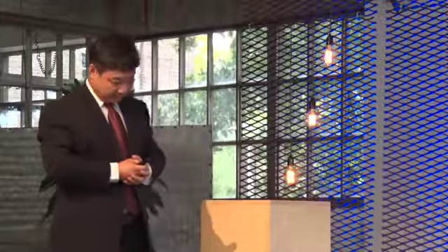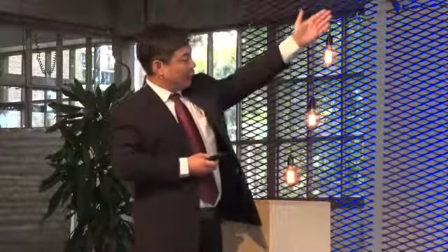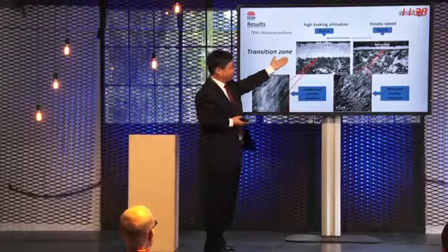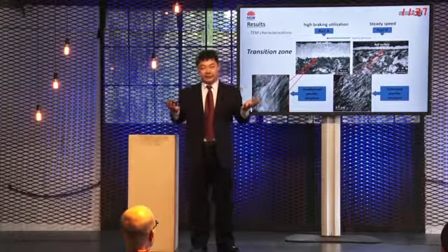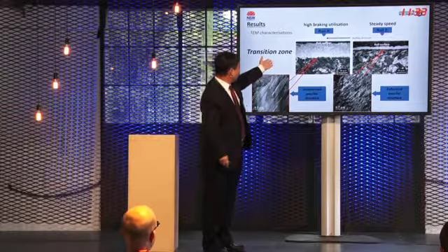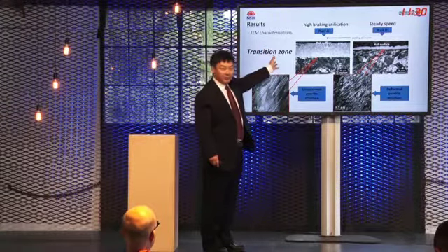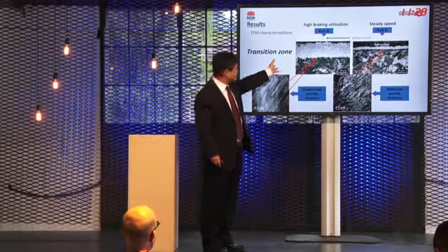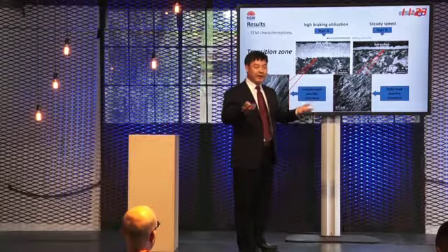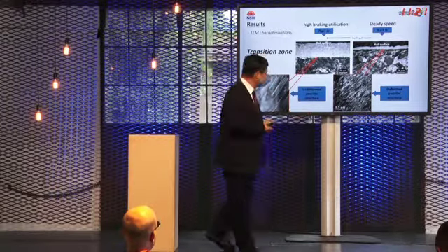Okay, now let's discuss some results. Rail A, the high braking area. Rail B, steady traffic. The top one is the white etching layer. First, visualize the difference in thickness. For rail A, the white etching layer is about 50 micrometers. For rail B, the steady traffic region, it is only 8 micrometers.